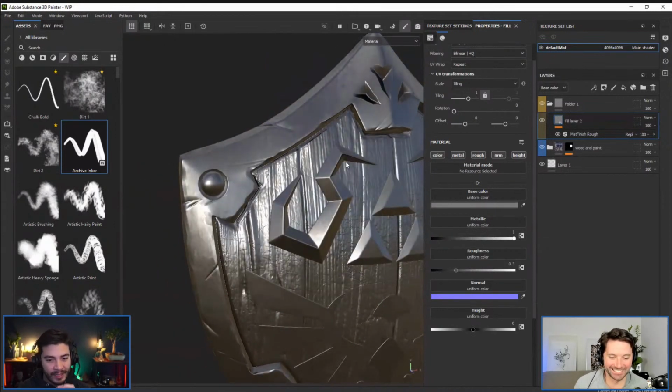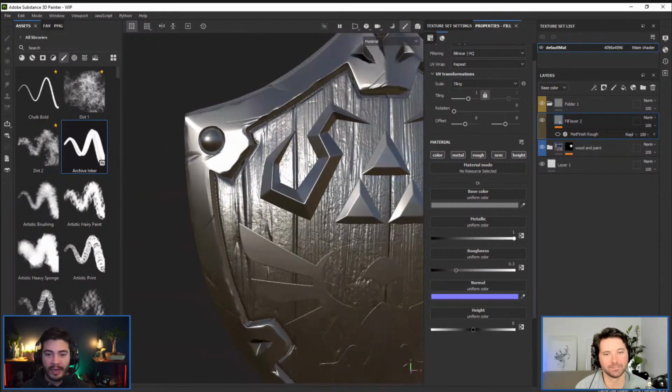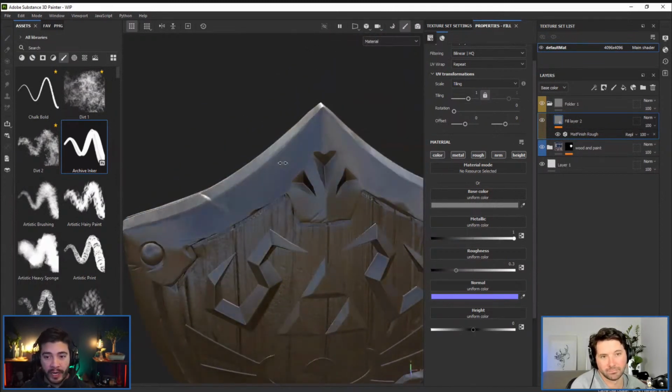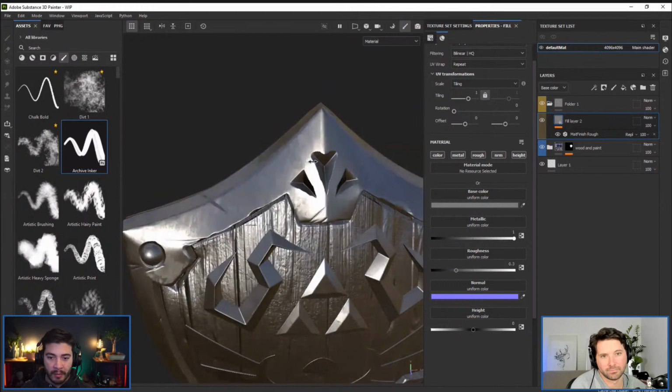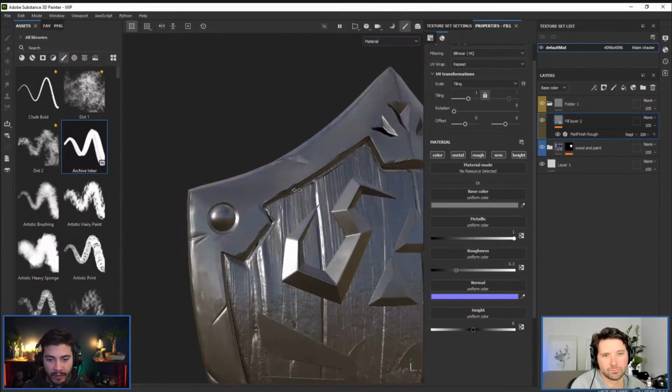Yeah, it's those subtleties. If I just turn off the matte finish, it is a metallic object, but there's no variation in the roughness. So it's very clean. And this is not meant to be clean. So I'm going to click on that. And you'll see now we have nice variation. By the way, I'm holding Shift and right click every now and again. I do this all the time just to change the position of the environment and the light, just to check that everything is looking cool.